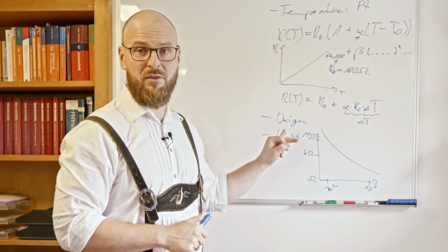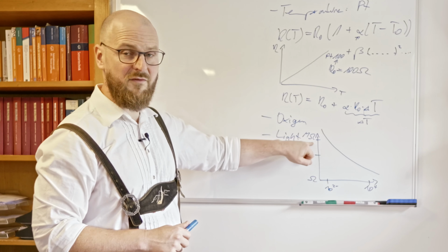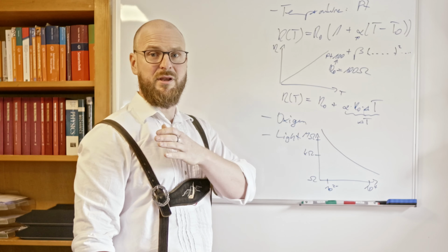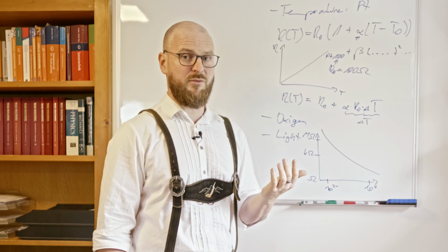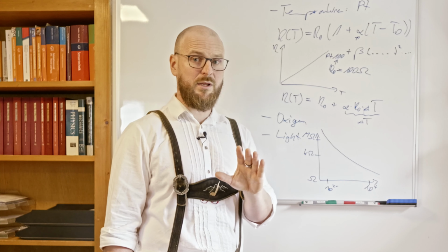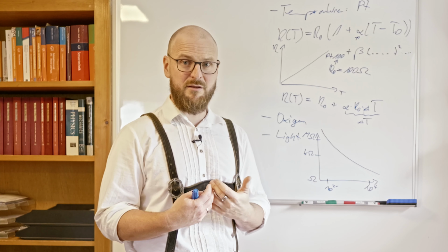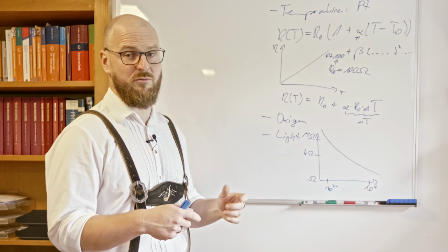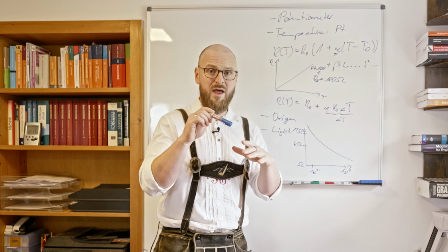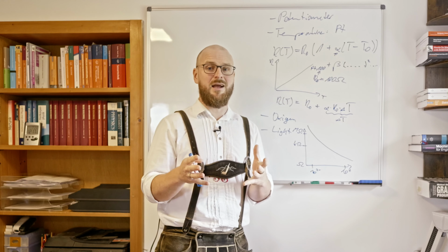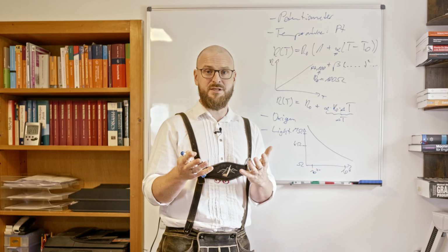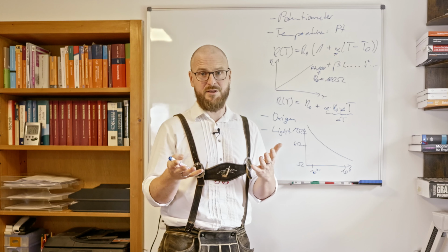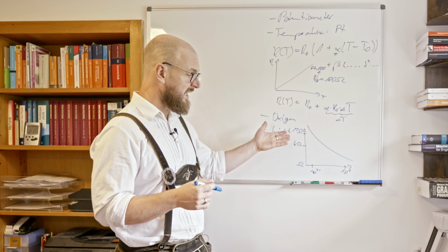That gives us some other problems indeed. Think of that mega ohm. Now measuring the voltage along a mega ohm resistance can be quite complicated because our measurement devices most of the time also have only resistances in the mega ohm range. So we get into that area where those systematic errors for measuring voltages and currents with real voltage or current meters get important.